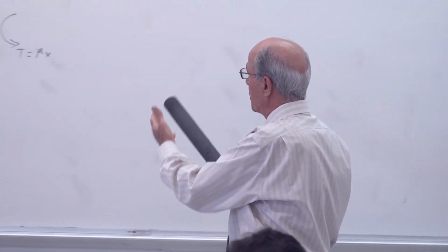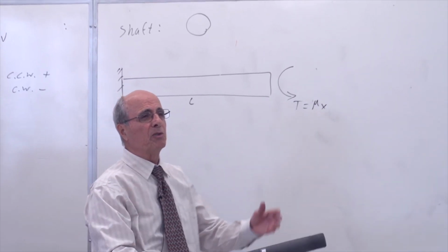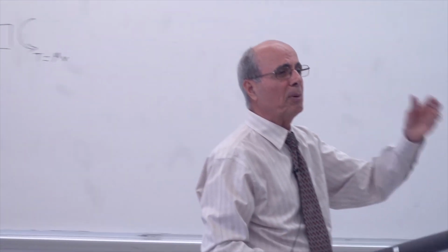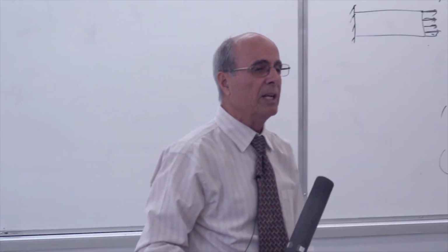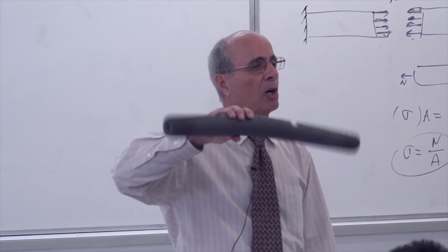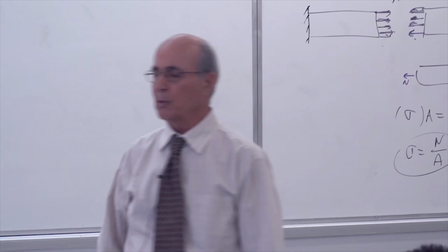So this is exchangeable. But for the discussion, we always put the shaft here in the x direction. So don't assume Mx is always the torque. One of the three components of the moment becomes torque. We discussed that before in lecture 1. And the other two become bending. Which one depends on how you put your shaft in the system. Is that correct or not? So that is the idea of statics again.